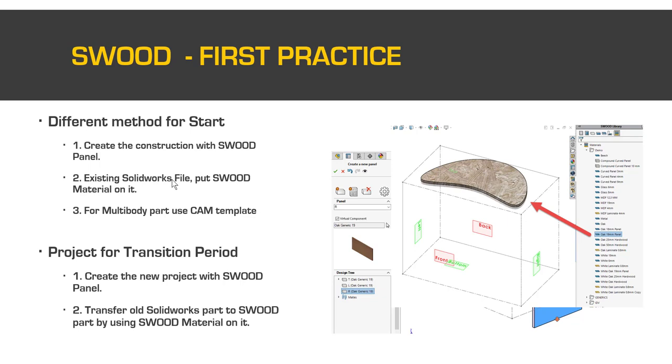Why do we talk here about 3 different methods to start? Because sometimes when you get SWOOD, maybe you already have SolidWorks. So for the old SolidWorks parts or assemblies, you can directly convert them into a SWOOD project just by using SWOOD material, or for some multi-body parts, you can directly input some machining template inside to directly generate one assembly with all the parts machining. Okay, now let us see what we can do exactly.